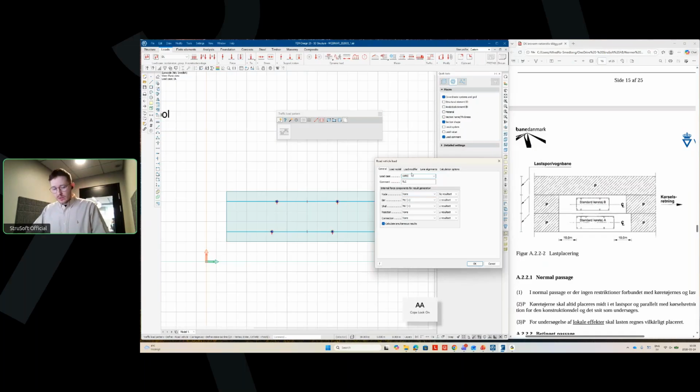So a bit briefly here, the load case name, let's go with webinar LM3A, since we're starting with the A vehicle. The TLC we can keep for now, and these are the types of results that we want to get from our analysis. And let's keep those as they are. Down here, you have an option whether you want to have all of the simultaneous results additionally to the main results that you ask for. But to keep the time a bit down here, we will uncheck this for now.